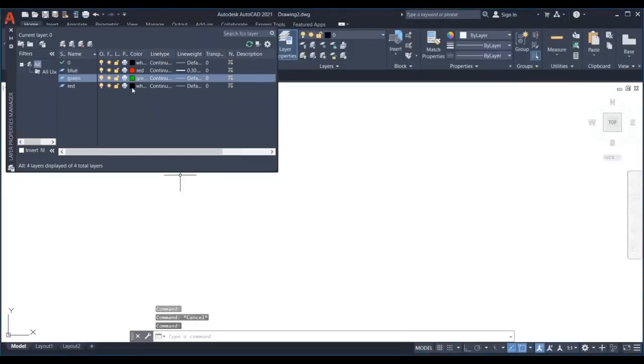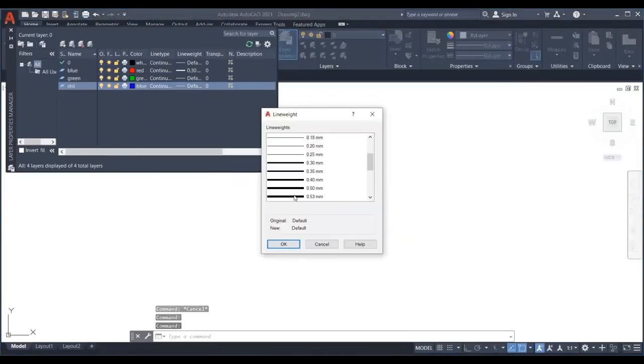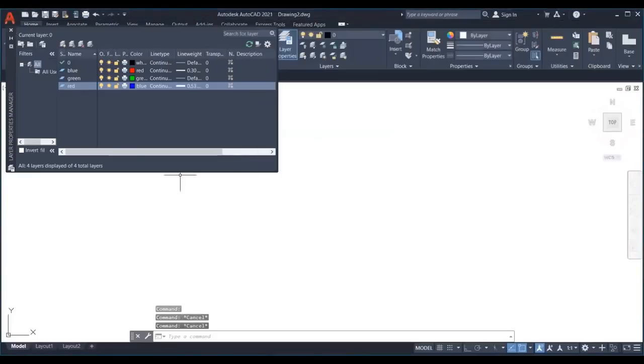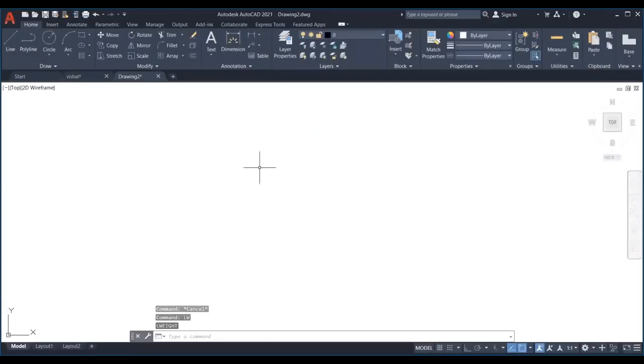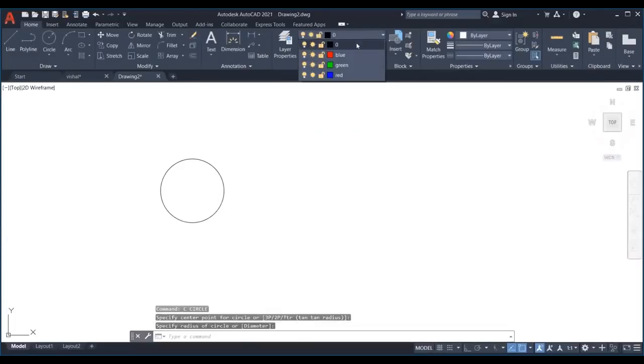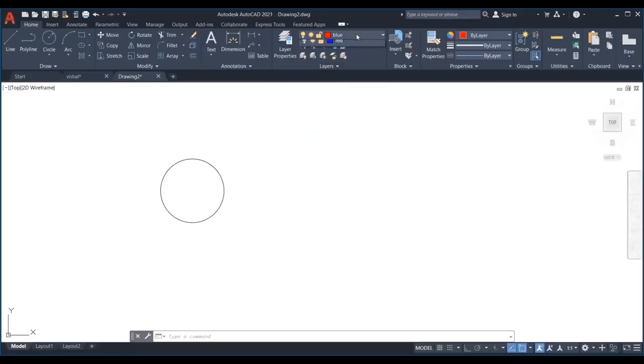Let us learn how to manipulate different layers. To put an object in a layer, make sure when you are creating that object, its layer is set to current. Let's understand this with an example. If we want to draw a circle in the layer named Small Circles, I will make sure I select it first before drawing.